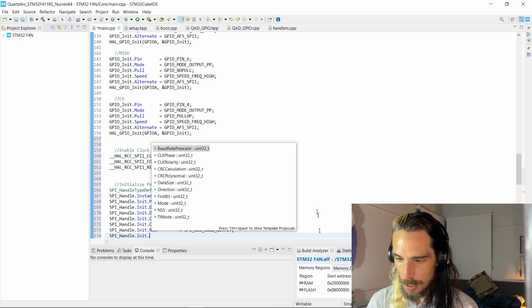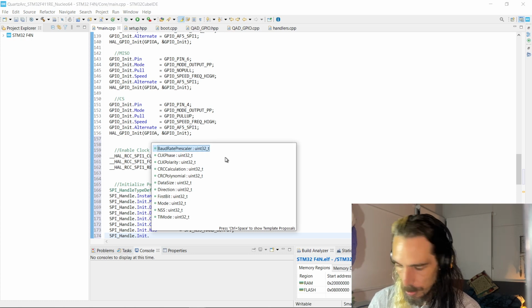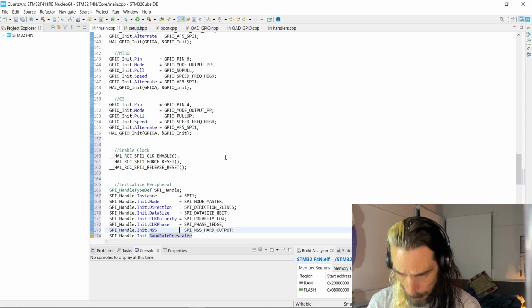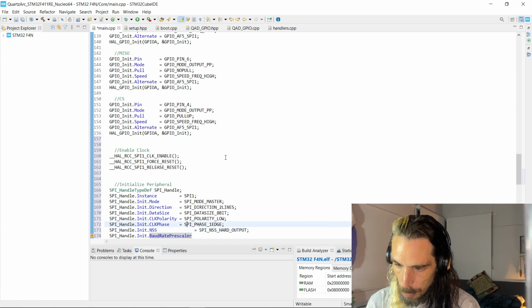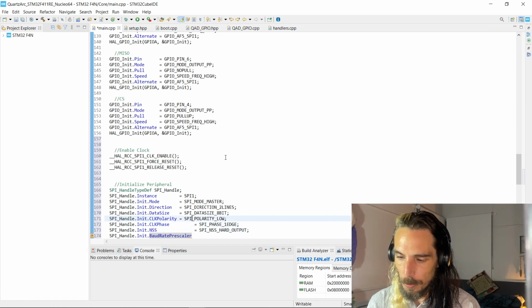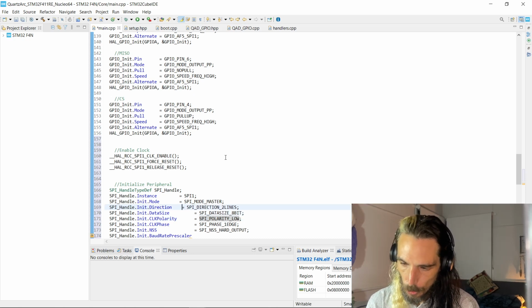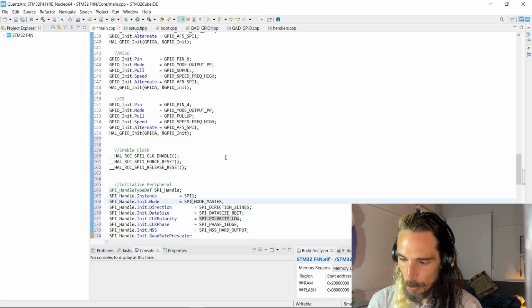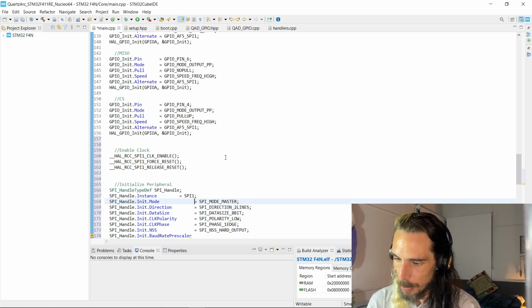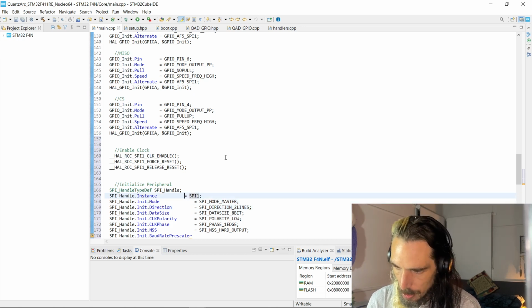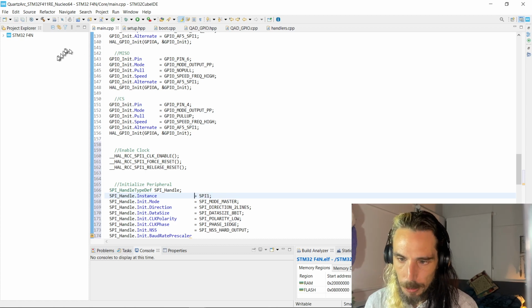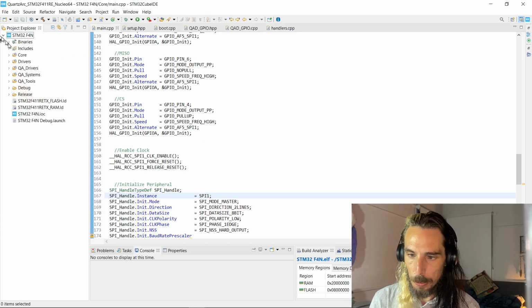We also need to let it know what speed it's going to be operating at. Now, this is based on the particular clock that is being provided to the peripheral. So you can select multiple different clock sources and go through and set those up as needed. We're going to stick with the clock as it is at the moment, just in its default operating mode.